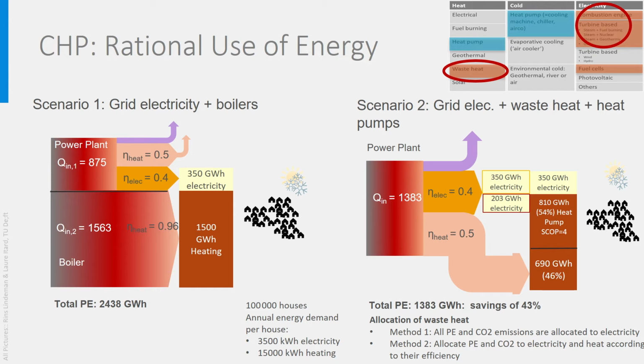See method 2. Next to waste heat from power plants, there are many other sources of local industrial heat that could be reused to heat buildings. They should be considered when designing an energy infrastructure. Also note that burning a fuel in a boiler just to make heat is a big waste of the potential of the fuel. It is much more logical to burn the fuel to make electricity and to use the produced waste heat for heating purposes.